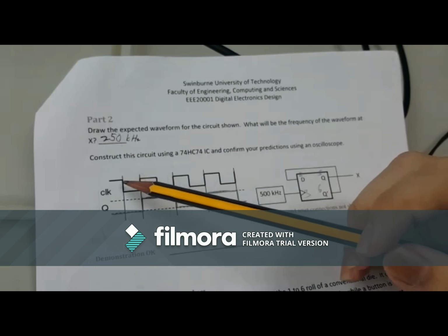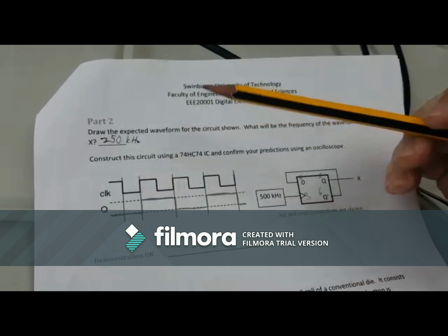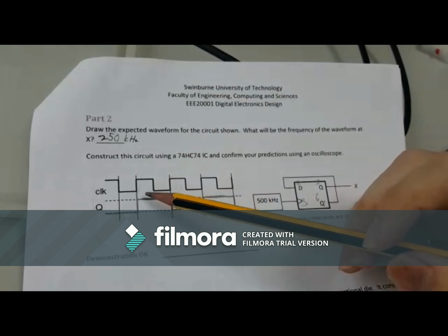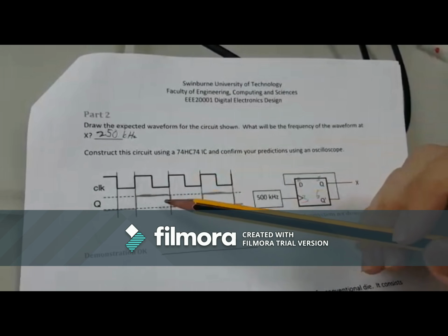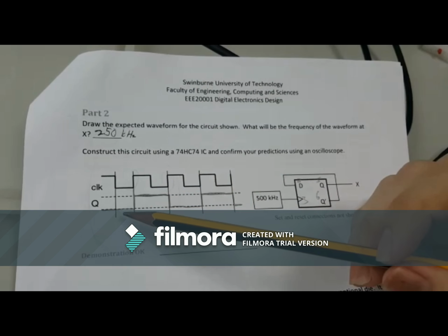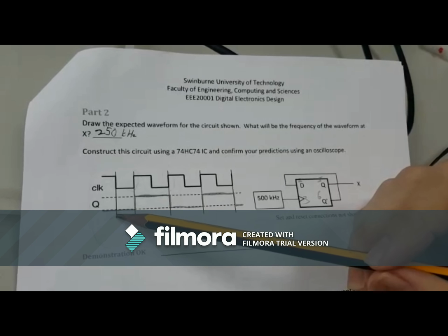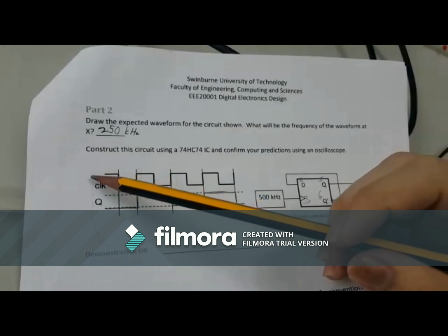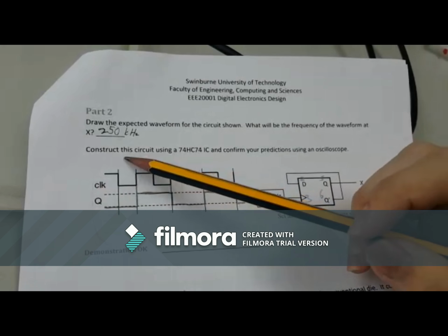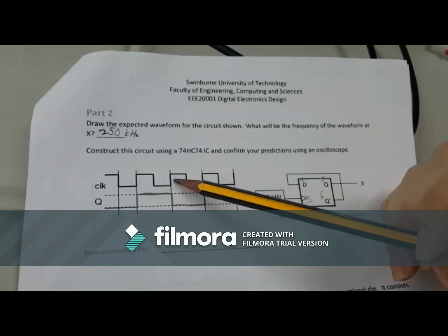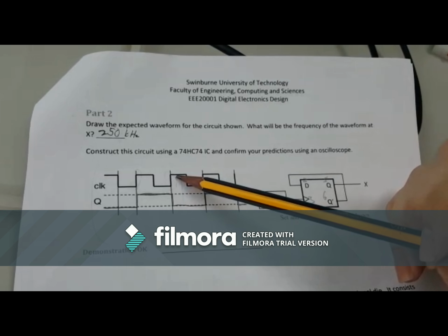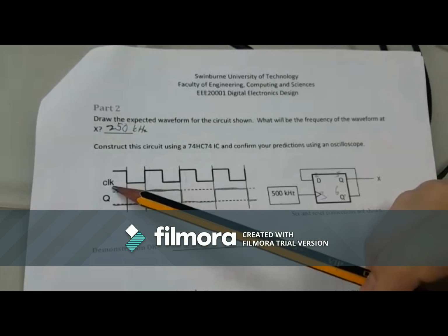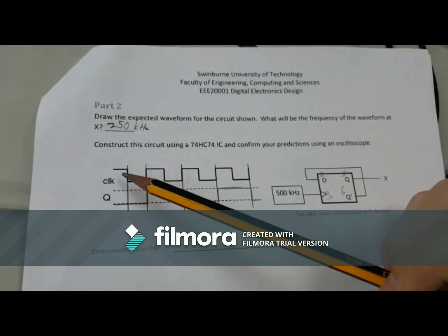We have constructed the circuit over here. So we want to prove that with a clock frequency of 500 kilohertz, we will get an output of 250 kilohertz. I will explain why. Because the rise of the clock module will cause the rise and drop of the output, one period of the output requires 2 periods of the clock module, which makes the frequency of the output half of the clock frequency.